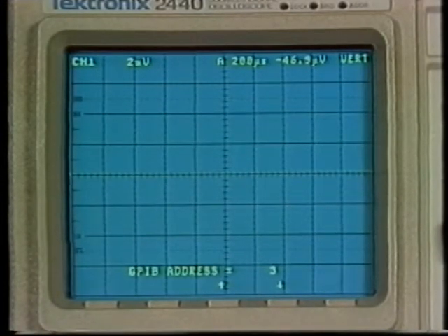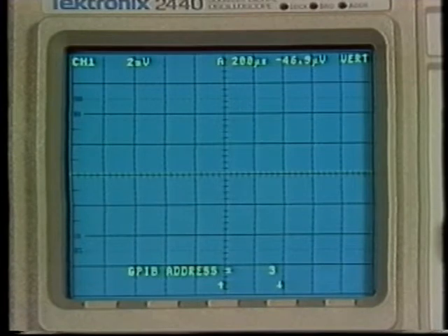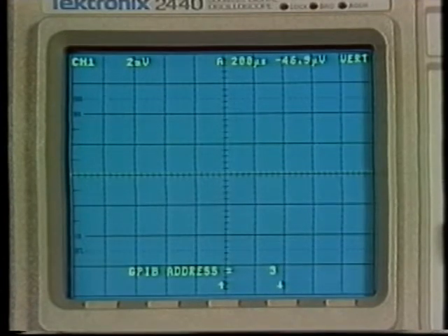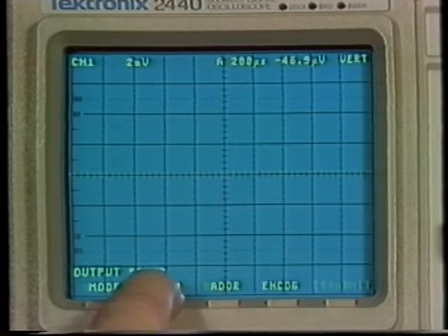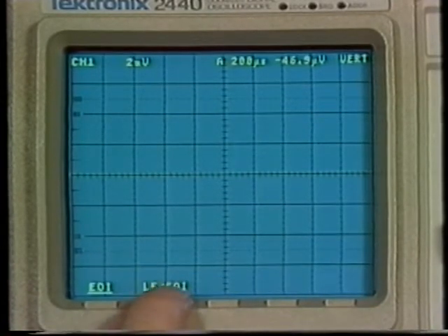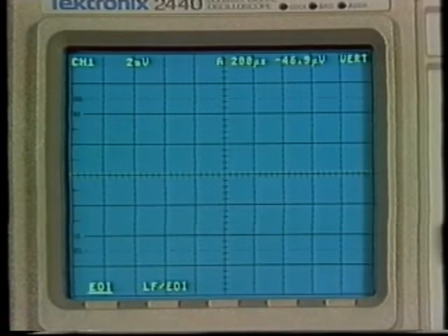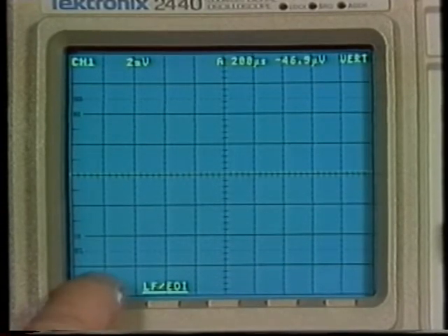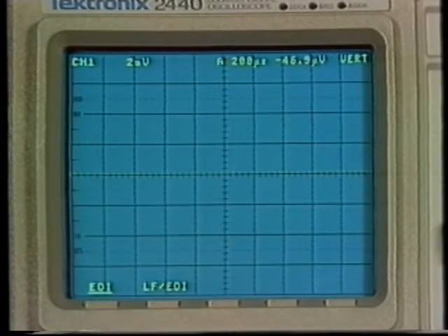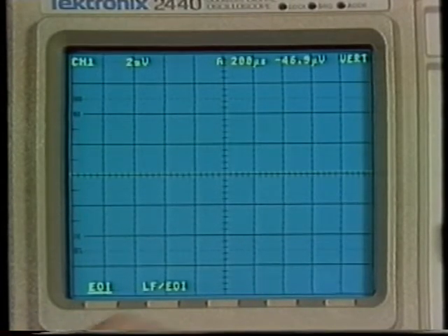the front panel Output button to access the Output menu, and then select Setup to re-enter the Output Setup menu to select Term. The Term submenu has two selections with the underline showing the current selection. Move the underline by pressing the bezel button under the menu item desired. EOI is the method TEC specifies in their codes and format standard. LF EOI will allow you to communicate with devices that use either EOI or LF.